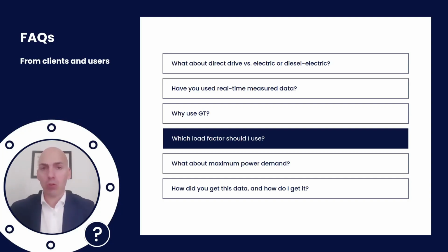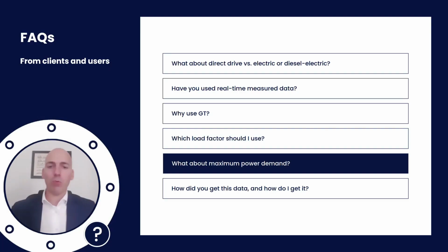Use the lower band in order to get low conservative estimates, and the higher band if you want to pop out the champagne, or if you are dimensioning for the maximum power outputs. But of course, if you have a single ship, use the auxiliary engine rated power as maximum, and then use average power for the revenue estimates. This is a nice bridge to the second one.